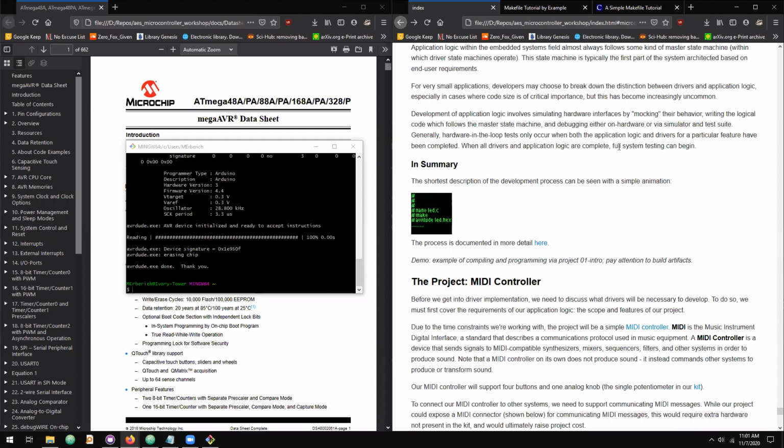Typically in industry, there's an order to development where you'll write your drivers after performing initial board bring up. You'll individually unit test those drivers as much as possible. So typically that'll be hardware in the loop. So you'll write some test image to your device that contains driver calls that exhaust its interface.